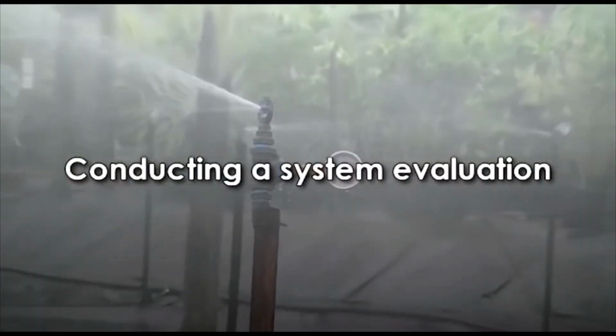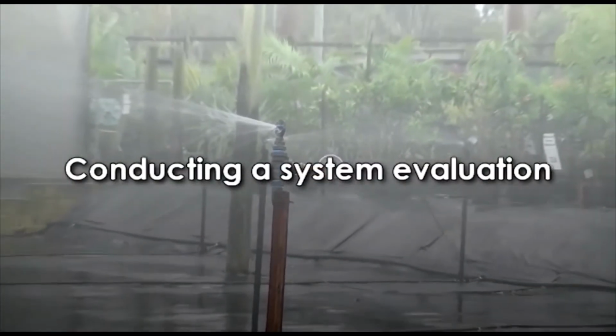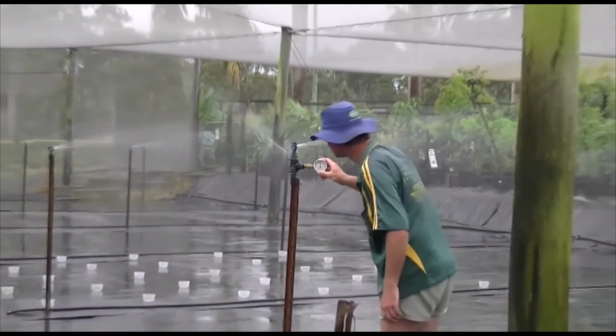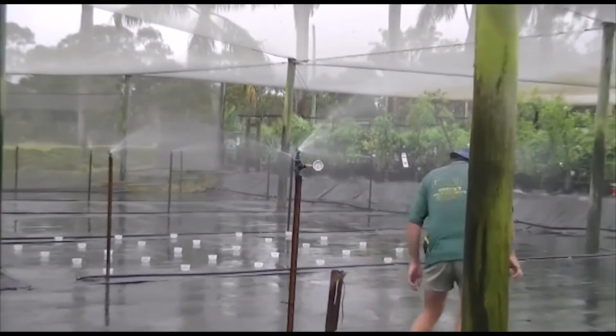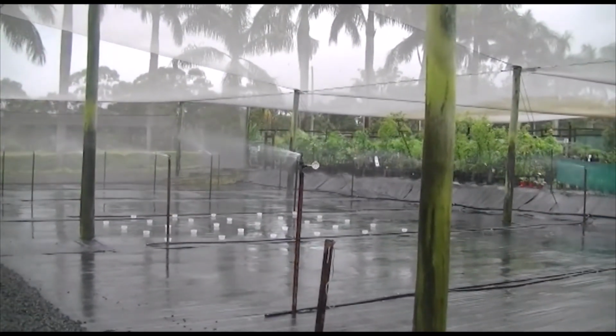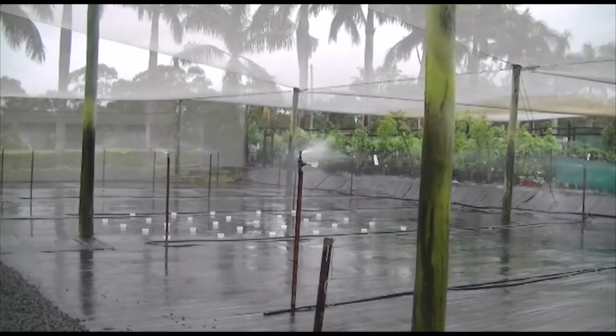A system evaluation involves making visual observations along with measuring and recording pressure and discharge rates of sprinklers. These measurements can then be compared with industry best management practice parameters and with previous test record measurements.